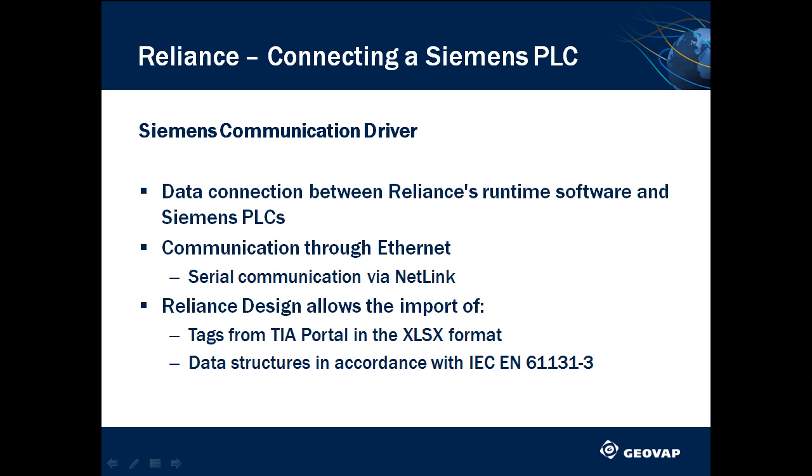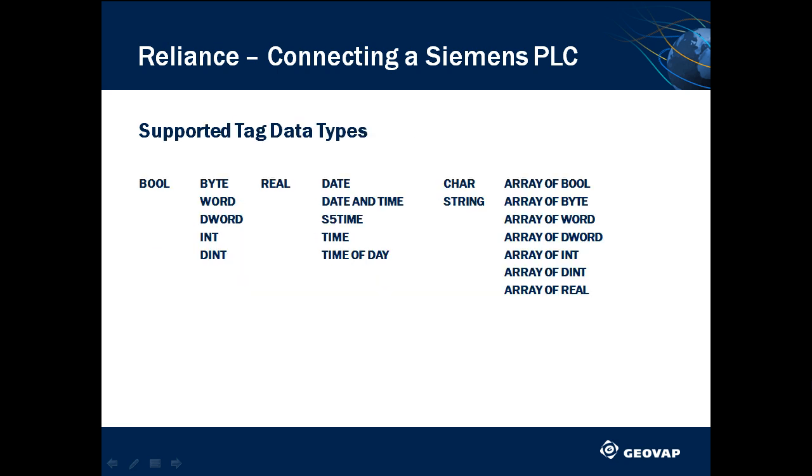The Reliance Design Development Environment also allows you to import both tags from the TIA Portal Development Environment in the XLSX format and data structures in accordance with the IEC EN 61131-3 standard. Here, you can see all the supported tag data types. In addition to simple data types such as bool, byte, word, real or string, it is possible to read datetime tags and array type tags.